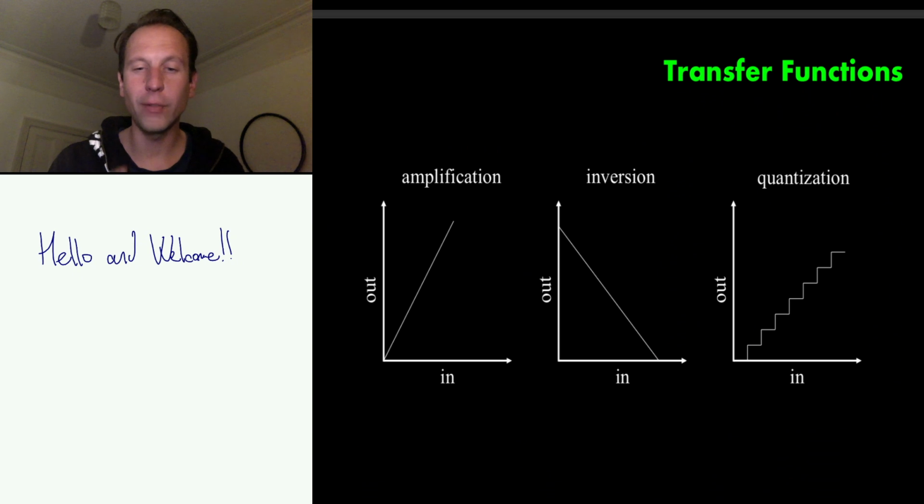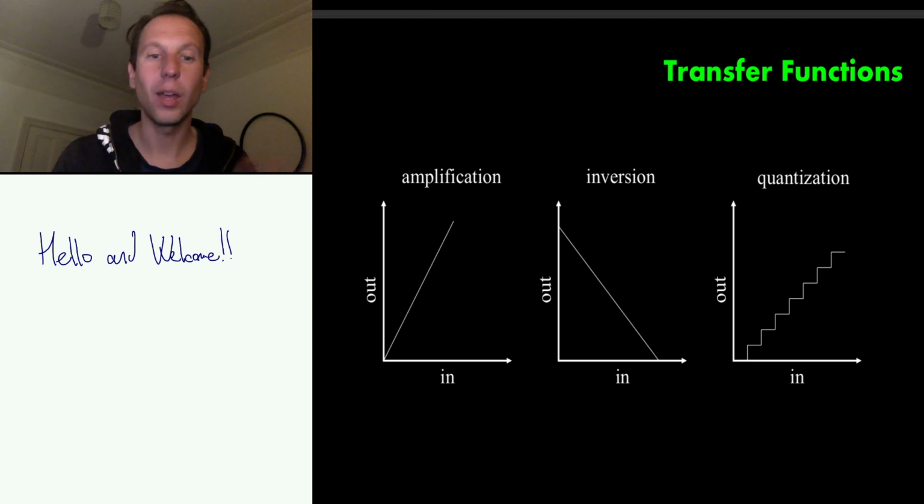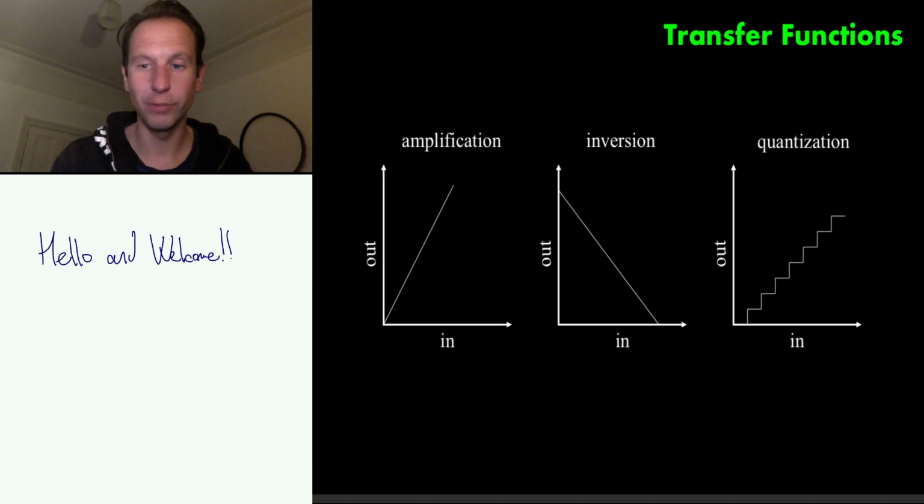So you see, if you have two input values which are really close together, it might be that for those two close together values, you get the exact same output value. So you get this kind of quantization going on. And what you see then is that quantization is not linear. Okay, a staircase is not a straight line, no matter the fact that it kind of takes that shape. Overall, it is crucially nonlinear, and that's where aliasing distortion links in, because you will necessarily have some extraneous, newly formed spectral components if you perform quantization.